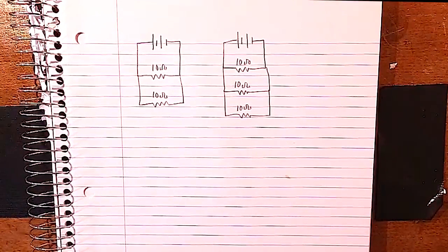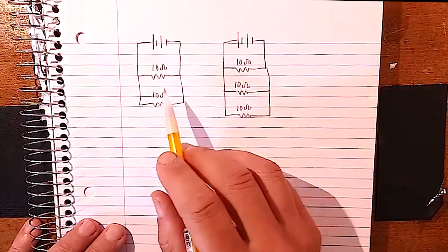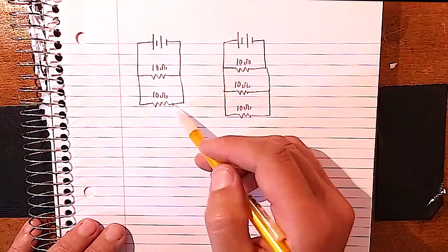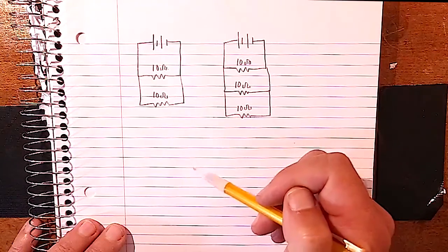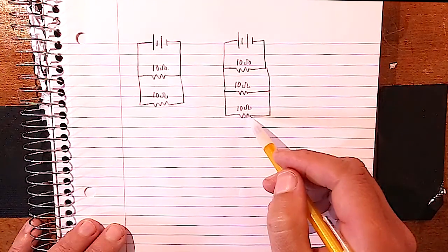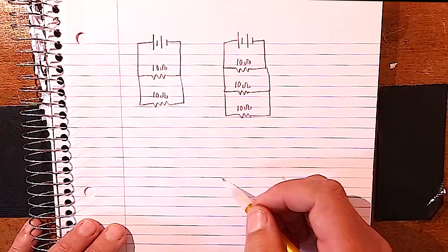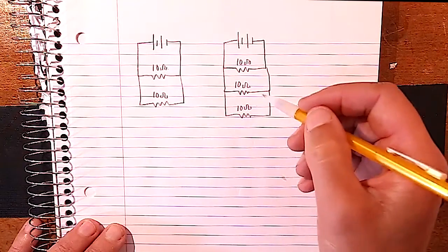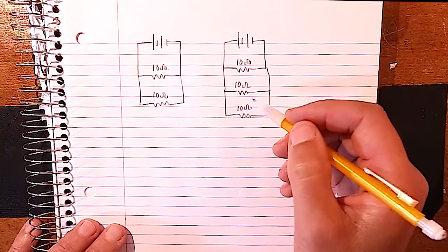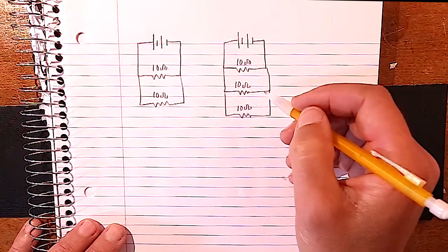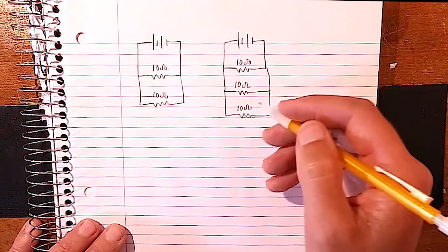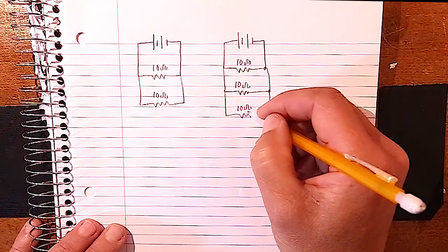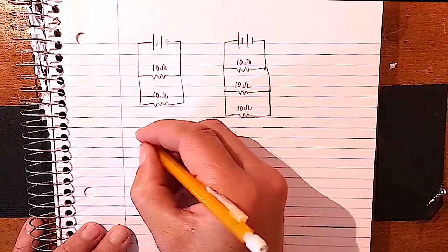This is counterintuitive, and it's a common question. Let's say we have a circuit, it's parallel because there's junctions, and we have two 10 ohm resistors in parallel. And the question is, if we add an additional resistor in parallel, what happens to the total resistance? Now, it sounds like more resistors would be more resistance, but it's not. More resistors gives us more paths, more options. So therefore, because we have junctions, we have other ways to go. An additional resistor actually makes the total resistance go down.